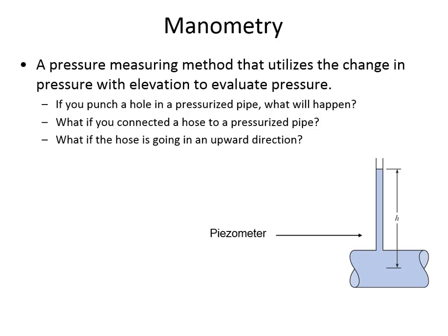And there was an incident here in Huntington, a water main break on the other side of the railroad tracks, where it took them more than 24 hours to actually find a valve that was serviceable. They, I think, uncovered 7 or 8 valves before it was finally maybe the 8th or 9th valve they tried that they could force closed, because they've got to close the valve before they can go in and patch and repair the pipe. So that's a long way of saying if you've got a pipe and there's a hole in it, water's going to be spraying all over the place because it's pressurized.